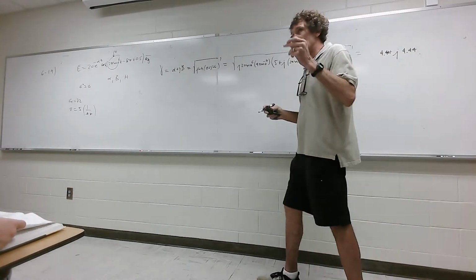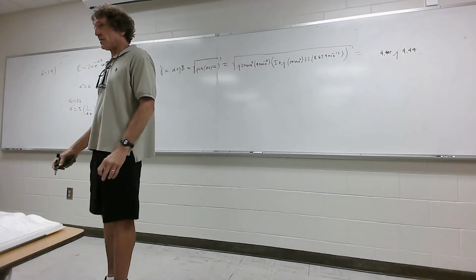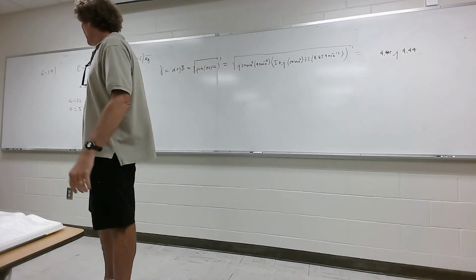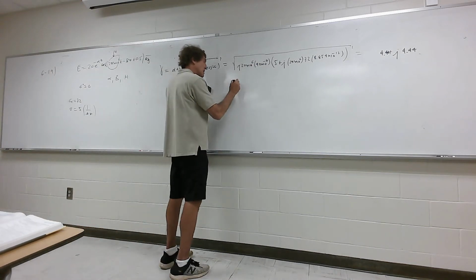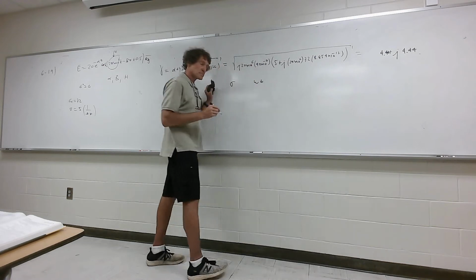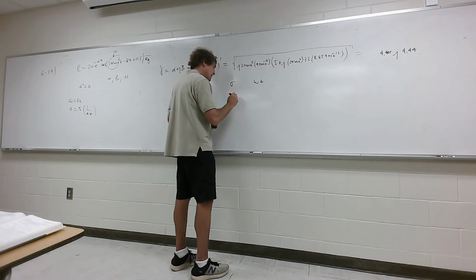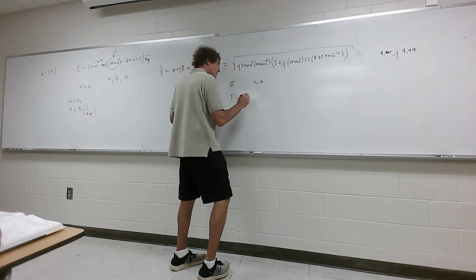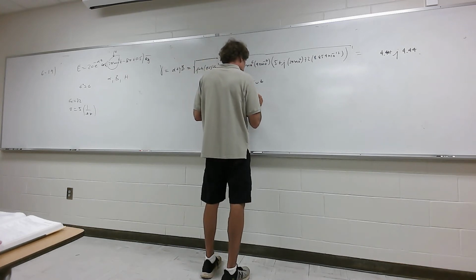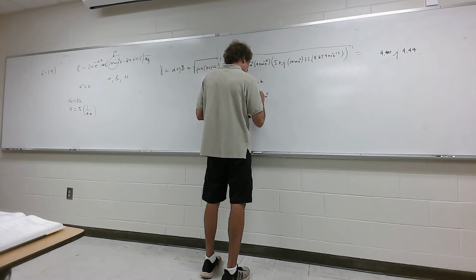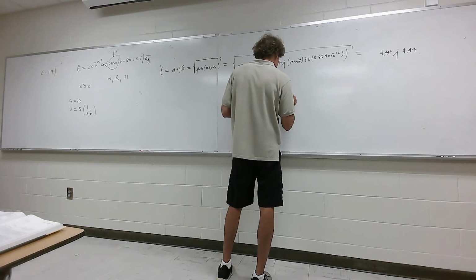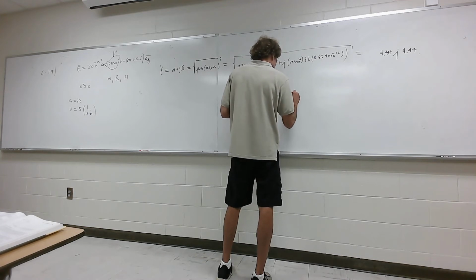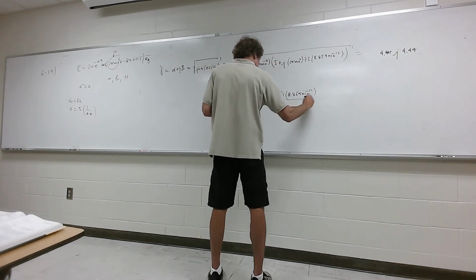Now, the minute you see alpha equal to beta, you know it's a good conductor. You all see that? But even before that, what we could do is compare sigma versus omega epsilon. Sigma is 5, isn't it? Omega is 2 pi times 10 to the 6th, then epsilon, which is 72 times epsilon naught, which is 8.854 times 10 to the minus 12. So just tell me what this amounts to right here.